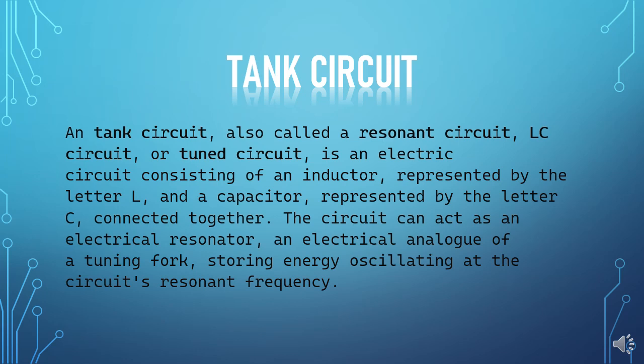My project is on tank circuit, also called a resonant circuit, LC circuit or a tuned circuit. Tank circuit is an electric circuit consisting of an inductor represented by the letter L and a capacitor represented by the letter C connected together. The circuit can act as an electrical resonator, an electrical analog of tuning fork, storing energy oscillating at the circuit's resonant frequency.